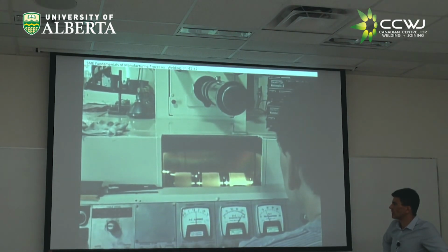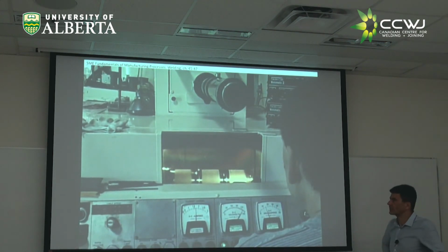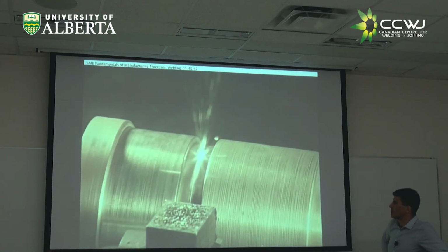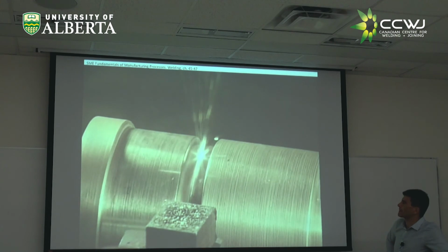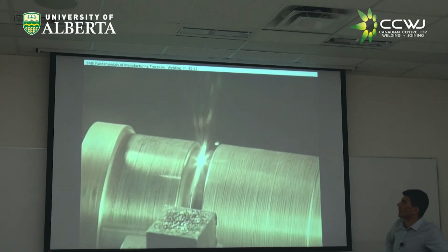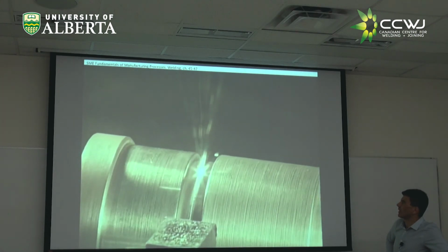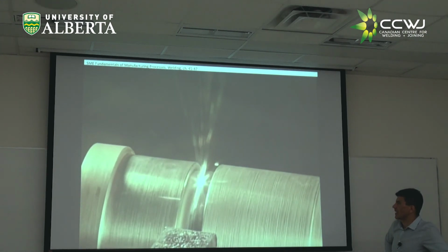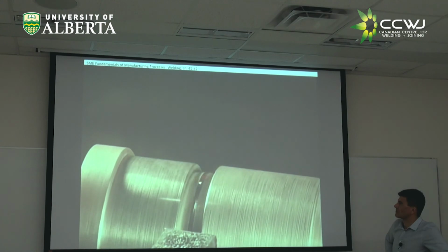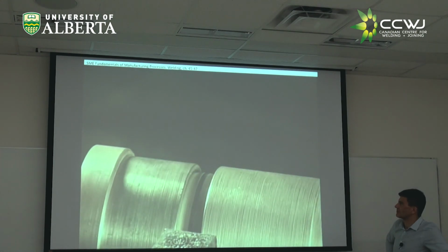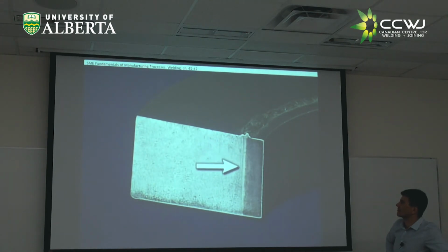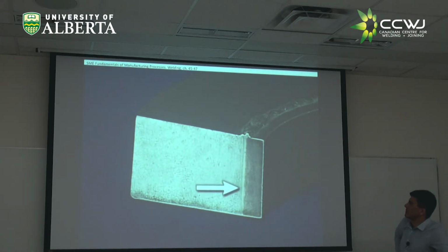This electron stream is developed in high vacuum, but actual welding can be performed in either high vacuum, partial vacuum, or standard atmospheric pressure. Because of the intense and concentrated heat generated, total heat input is low, minimizing heat-affected zone size and part distortion. This also allows for the creation of extremely deep and narrow welds.